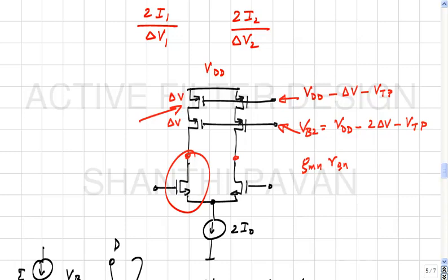Okay, so now once we find that the cascoding trick works, it's natural to become greedy and say, hey, why don't we? Sure enough, let's try. Let's see what happens when we do. So any comments on this? To increase VDD to support? Okay, fine. What else? Is there a more fundamental thing? So what can you say about the input and output common modes of the transconductor?